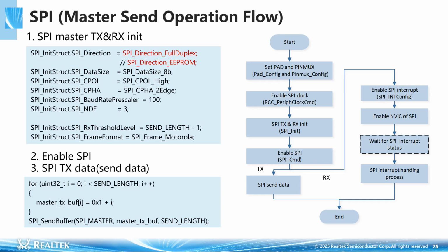Set the SPI transfer mode. Set the SPI data frame size. Set the SPI clock polarity. Set the SPI clock phase. Set the SPI speed. Choose which serial protocol to use for data transmission. Step 4. Enable the SPI.